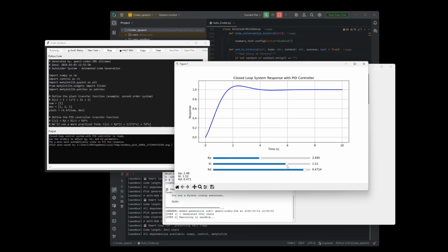So there's our error gone down to 0, more or less, no overshoot. And I can make it faster by increasing the proportional gain, so I get a faster rise time, or in the frequency domain we'd say it's a faster bandwidth. You see the time taken is less now as I increase the gain, so it's getting there faster, but I've introduced overshoot, so I'd need more derivative action to get rid of that, but I've run out of derivative action, so I could turn down the integral action a bit. I'll actually turn down both of them.